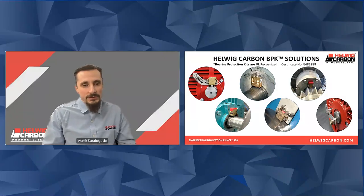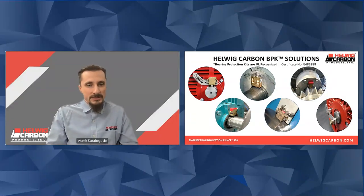Here are a few different types of our bearing protection kits and different types of installs as well. The bearing protection kits are UL recognized, and the certificate number is E485288. As you can see, there are a couple of different ways of installing these kits. In the far bottom right picture, we have a motor with a small stub shaft where we cannot go axially because there just isn't enough space, in which case we developed a bracket where we can go radially on these kits.